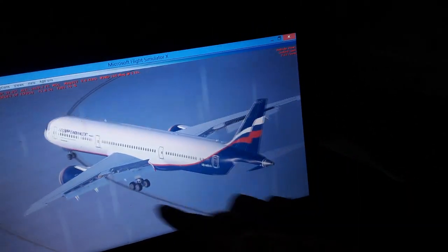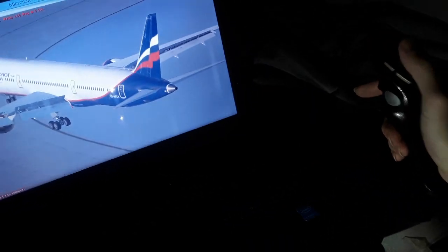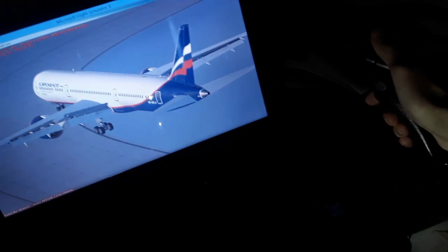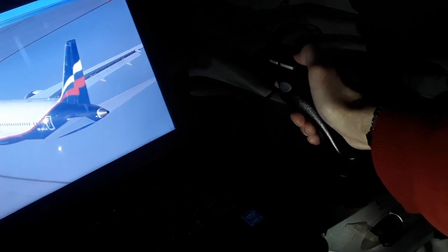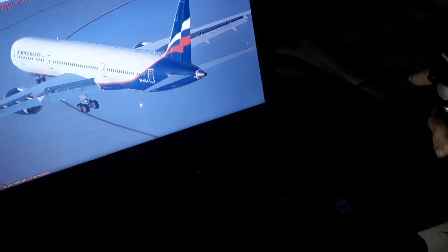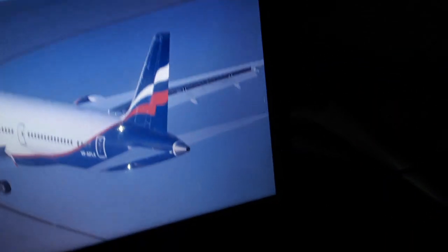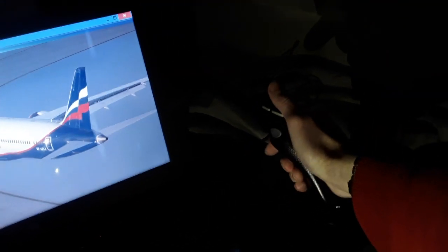Also we have another axis here, from wingtip to wingtip. Over here is the lateral axis. It's the axis we control with the side stick in the Airbus for climb and descent like this. You can make climbs and you can make descents of the aircraft using the elevator, and also the elevator pitch trim switch. You can trim the aircraft elevator to balance the aircraft in flight. So this is the pitch trim and the elevator control, the pitch attitude in flight, pitch up and pitch down, the side stick up and down in the Airbus, back and forth.